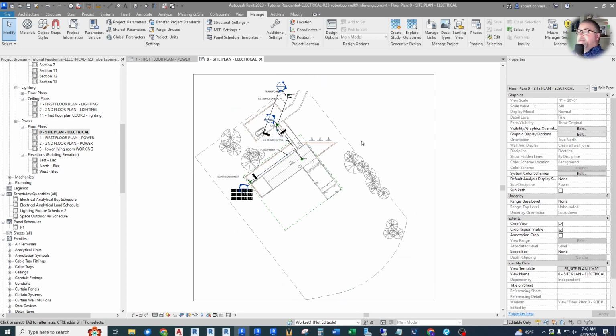This ends up being the same thing we did by manually rotating our view, and I really wanted to show you in that video how to rotate a view for other reasons if you need to, but this is actually the best workflow to accurately set up your site plan such that it is properly oriented. So I just wanted to cover that and show you this is the actual best method for moving forward.